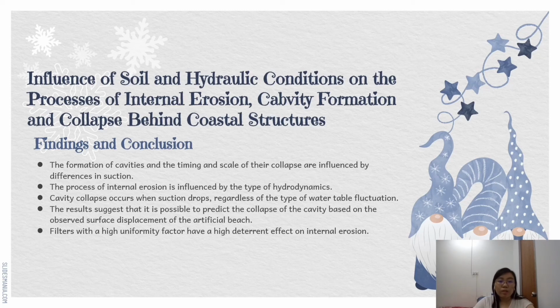The formation of cavities and the timing and scale of their collapse are influenced by differences in suction. The process of internal erosion is influenced by the type of hydrodynamics. Cavity collapse occurs when suction drops, regardless of the type of water table fluctuation. The results suggest that it is possible to predict the collapse of the cavity based on the observed surface displacement of the artificial beach. Filters with a high uniformity factor have a high deterrent effect on internal erosion.